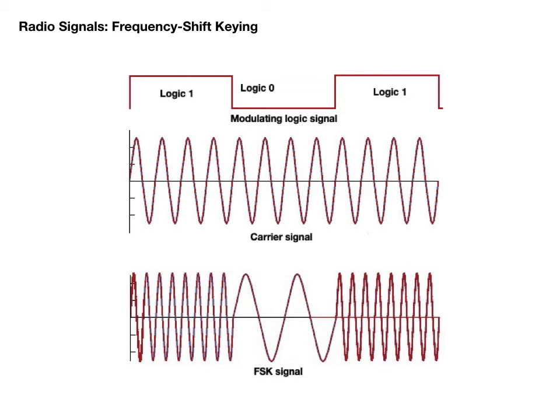When using audio frequency shift keying, it's typical to use an audio frequency of 1,445 Hz for the mark frequency and 1,275 Hz for the space frequency. Data is typically transmitted at 45.45 baud on the high-frequency bands. While this is a relatively low baud rate, it does keep the bandwidth down.